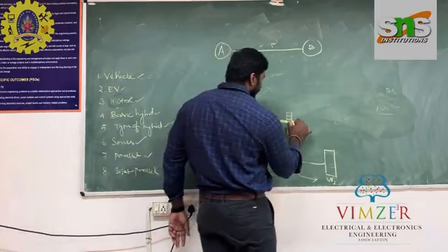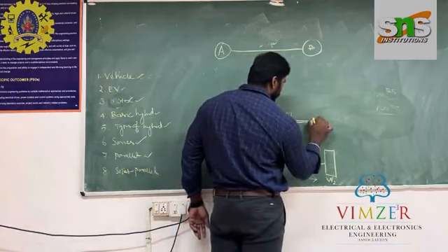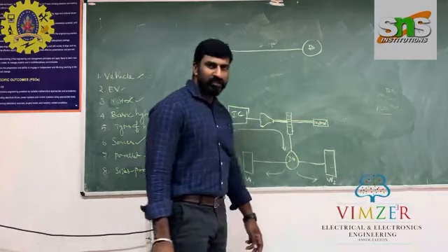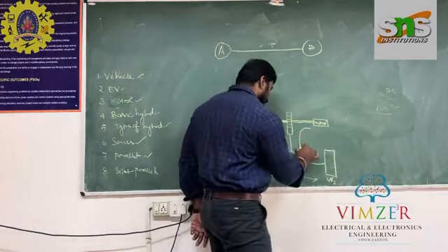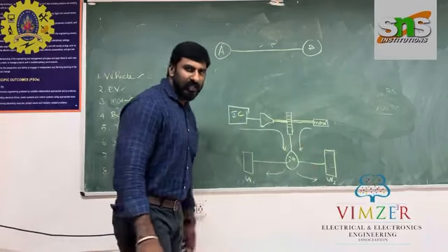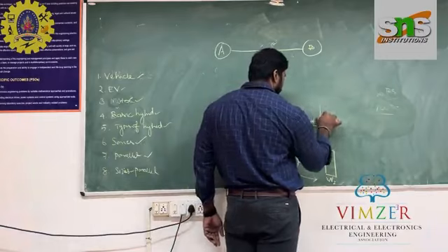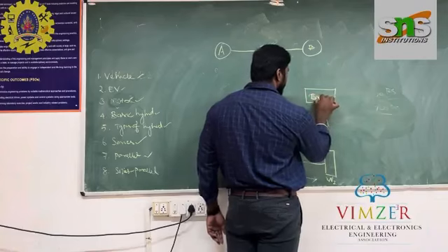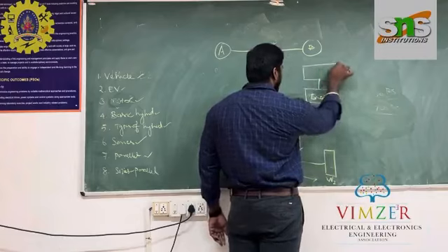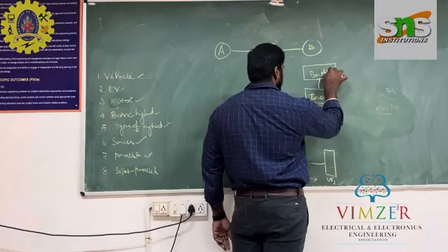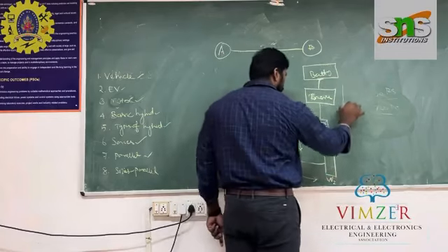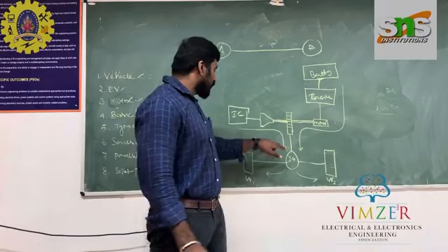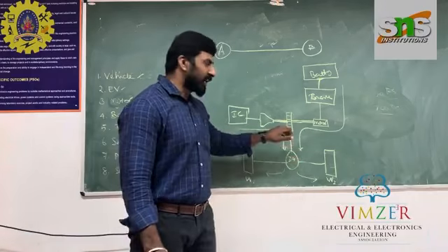And we also have another source: this shaft is connected here to a motor. So at the same time the motor also delivers power, and the motor also gives power to the wheels. At the same time the motor needs a power supply. That's why I am fixing this battery and inverter here. The inverter is supplied by the battery. So the power is transferred like this. One vehicle runs on 2 different sources at a time with the help of the gearing mechanism.